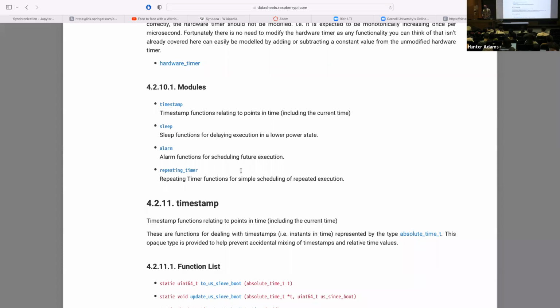At the lowest level, you can write to one of these alarm registers. When there's a match between the alarm register and the timer, an interrupt is thrown. If in that interrupt, you rewrote the value of the alarm register to be what you presently measure plus the same increment forward, you could schedule that interrupt to be thrown again. So you could, strictly through register manipulation, set up a repeating timer interrupt. The SDK has abstracted this for us, and this is what you've used in Lab 1. Under the hood, it's doing something like that, but it's making it easier for us to do the development.